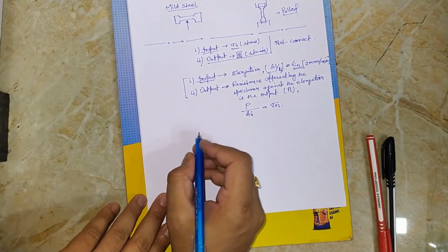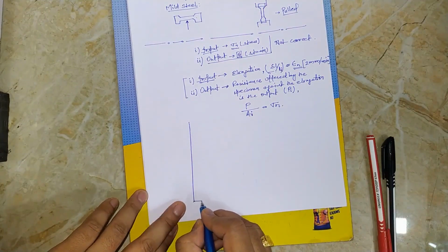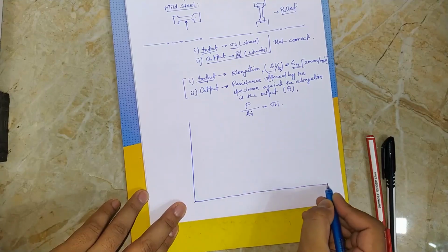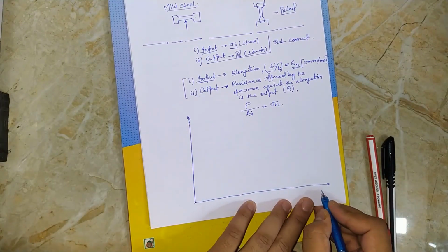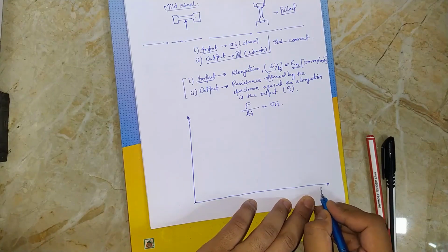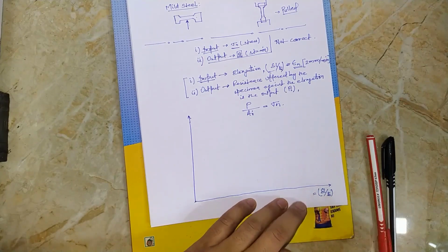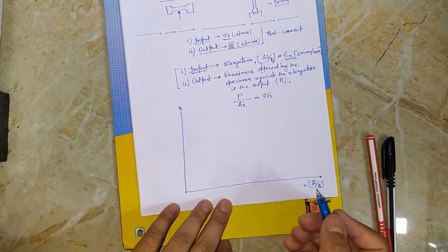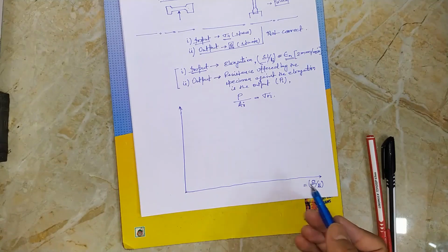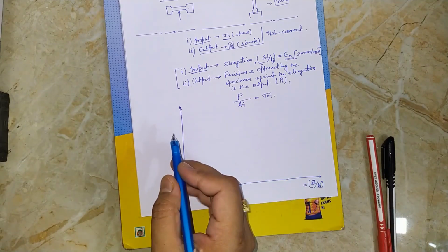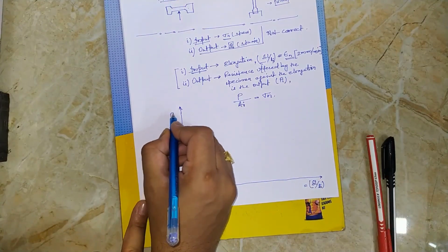So now we have defined the coordinate axis against which the stress strain diagram can be plotted. So here is the coordinate axis. On the x-axis we'll take elongation divided by initial length, just to match with the textbooks, because the basic input that is given to the specimen by the machine is elongation, and the basic output that is obtained is the load in terms of resistance. So that is only the basic input and output.